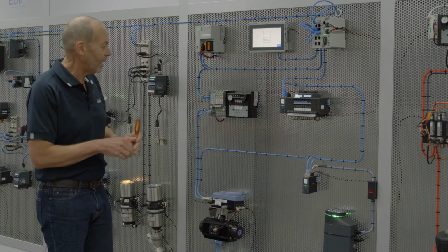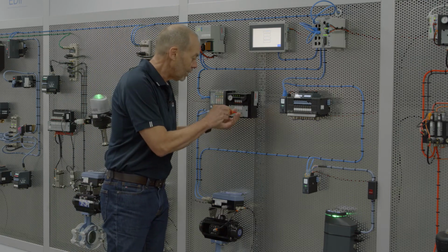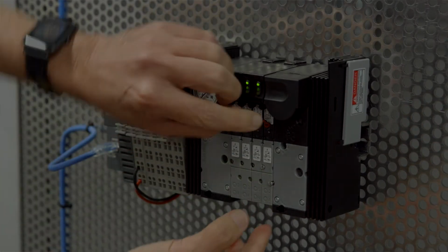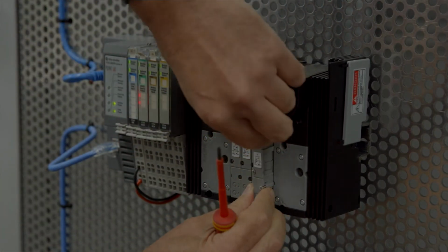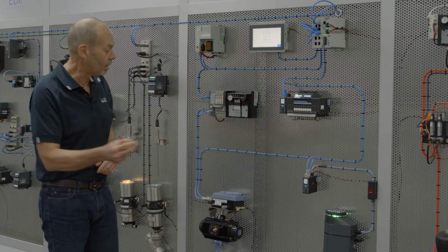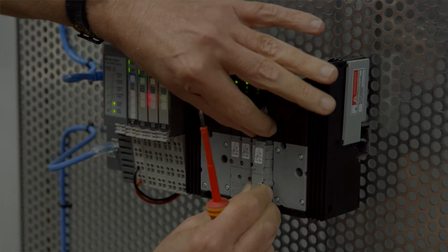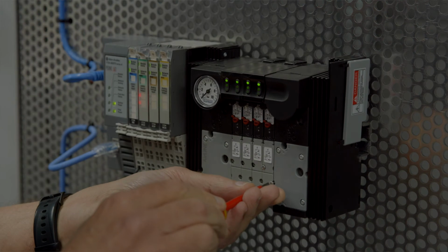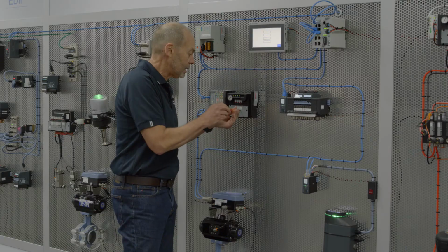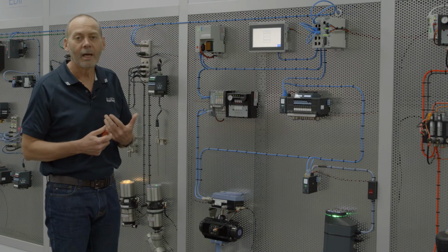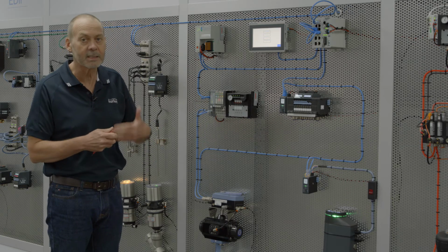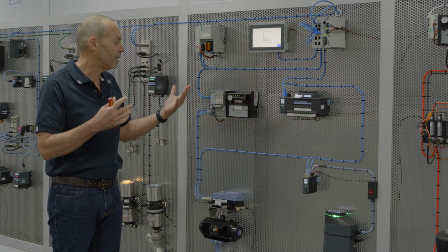We've done exactly the same with the Bürkert valves. We have the option of having a full hot swap capability to swap out valves under full operational conditions, so full air and full electrical connection. And of course, you can replace the valve and get back up and running in a very quick period of time. We do this as Bürkert is designed to run in the process automation industry. And in process automation, you have things like fermenters and distillation, etc. You can't turn those processes off.